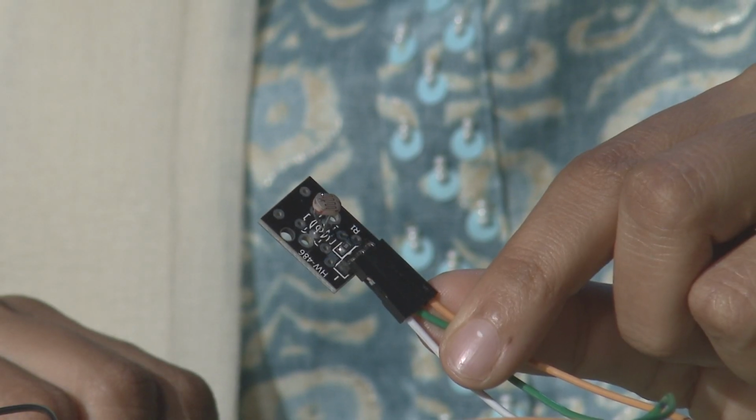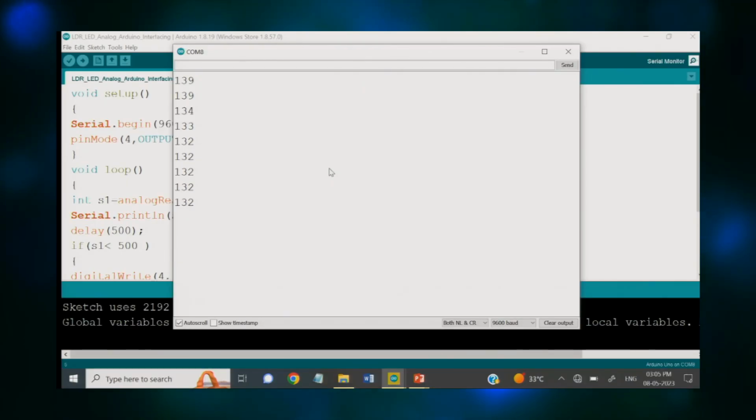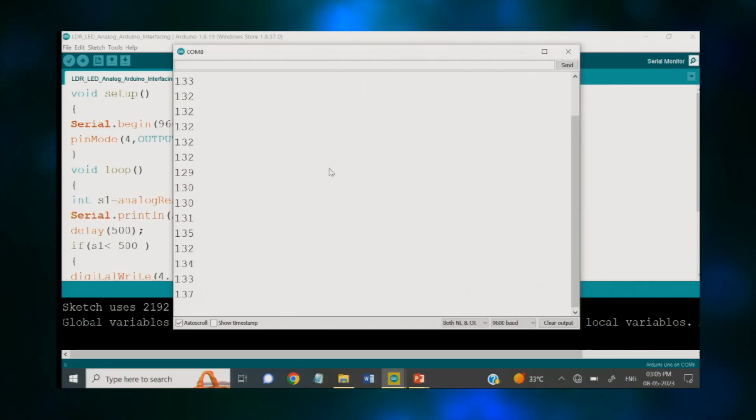So, currently you can see this LDR we have here in hand, and it is showing continuous values of resistance on your screen. This is considering the light intensity at this particular position. Now, let us assume a case that you are designing this particular circuit for a light control system, whether it is outdoor lighting or indoor lighting. So, let us consider an outdoor lighting system, the same as street lights you are trying to create. So, when it goes dark outside, your LED or that street light should turn on automatically. So, it means when your LDR gets into a dark position.